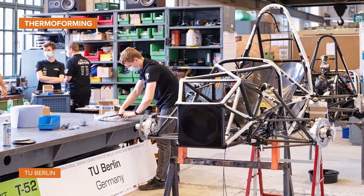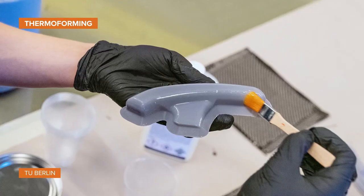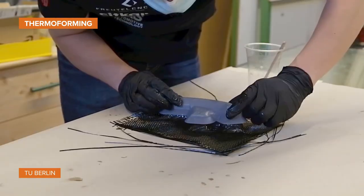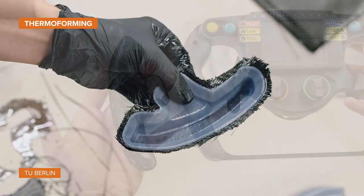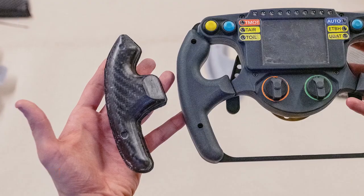The Formula student team of TU Berlin hand laminates carbon fiber parts on 3D printed molds for racing cars. Printed with tough 1500 resin, the mold is not only strong and supportive during the layup, but also sufficiently flexible to separate the part from the mold after curing, unlocking design possibilities.